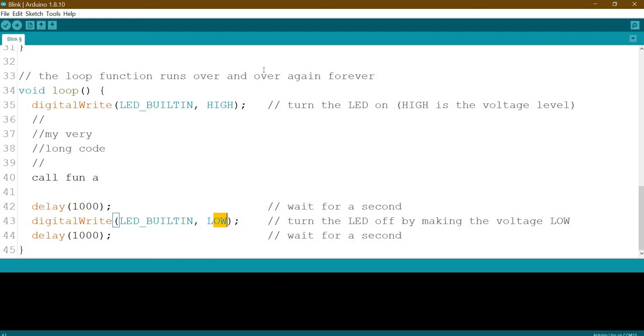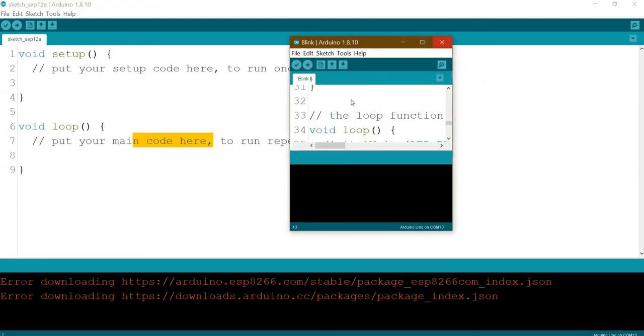But for the Arduino, unfortunately, until now we don't have a debugging function. So we have to simulate the debugging by using a serial monitor. Serial monitor is actually a very strong and useful function they provide us, so we can use it to debug our code.